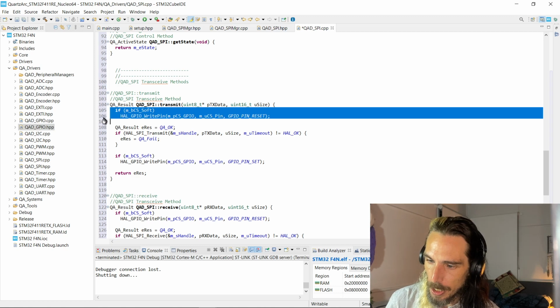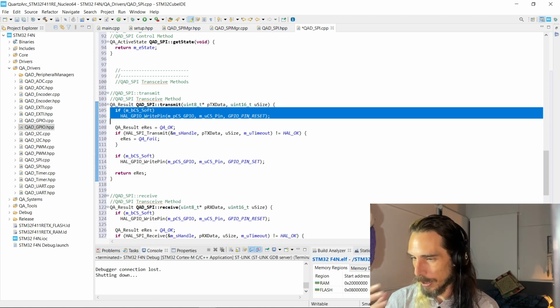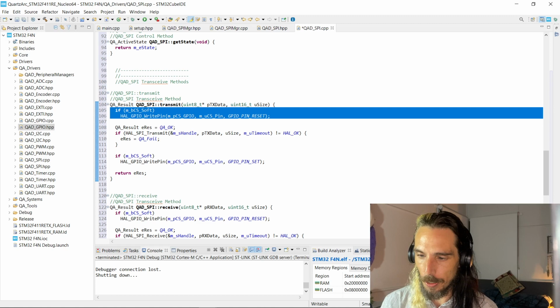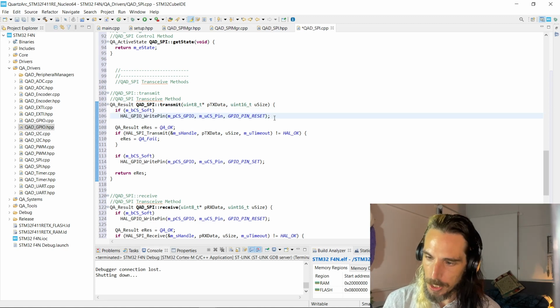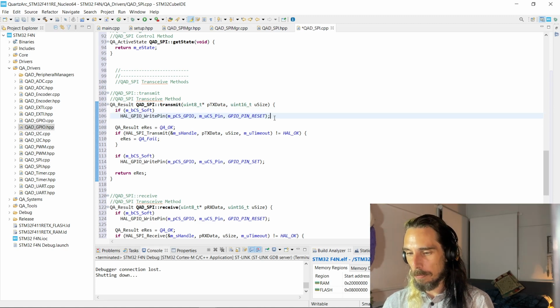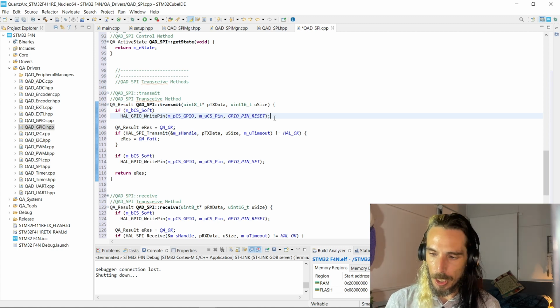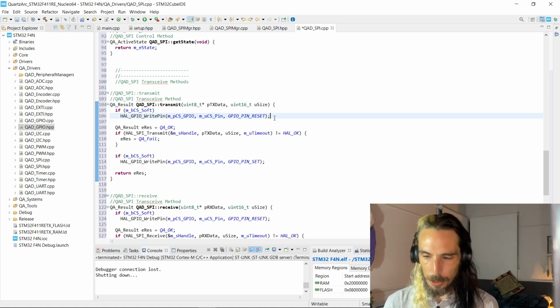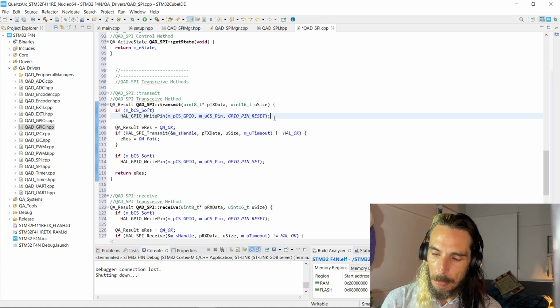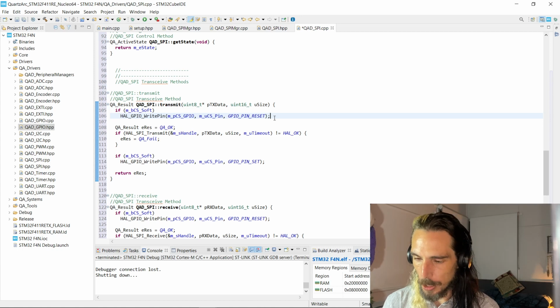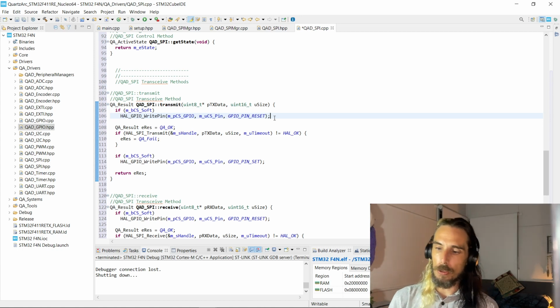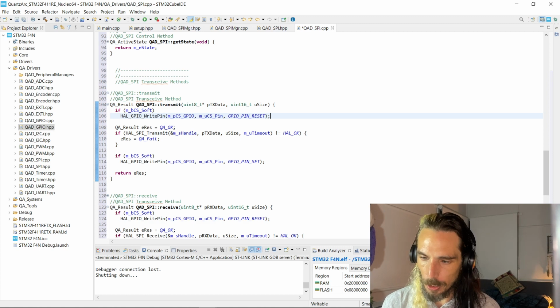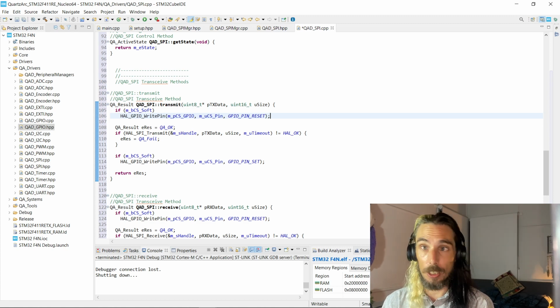In that case, essentially when we go to initialize it, we're going to do it that way, so you can kind of see how that works when we go to test it. But it basically means that we have the option of either getting the peripheral to do it in hardware, we can get the driver to do it in software if we're only connecting one device up to the SPI bus, or if we're hooking multiple devices up, we would actually tell the driver that we don't want it taking care of it, and we would actually do that manually outside of the driver whenever we want to communicate with a particular device.